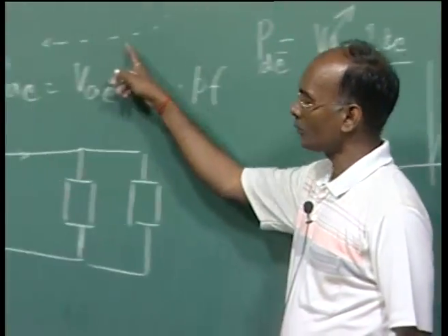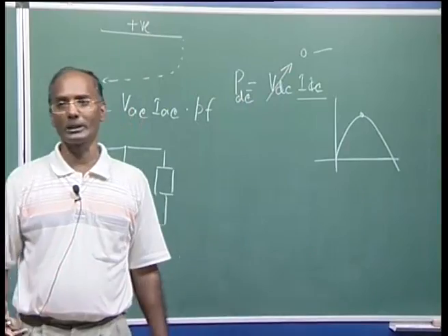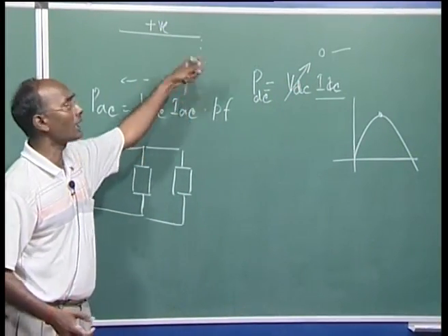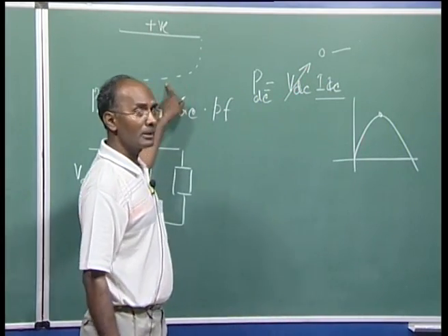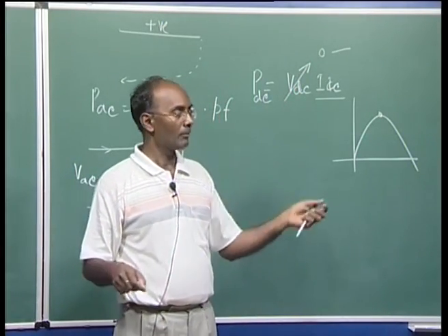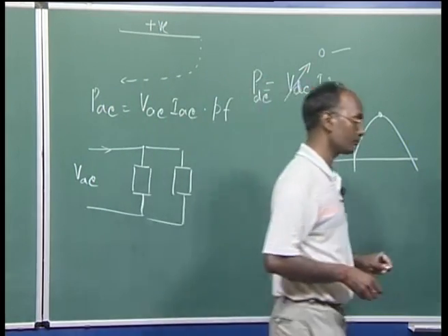We will see, although this is an advantage, it is normally used rarely. It is used only in emergency conditions. Because even though you are using ground here, there may be so many pipes and other things underground, that will cause erosion and corrosion in that system. So it is used only during emergency conditions. Suppose there is some fault in the system, then we can use ground as a return. And also to make this possible, we'll see the grounding rods, etc. Those are used in the substation. We'll discuss them when we discuss the components of the HVDC system.